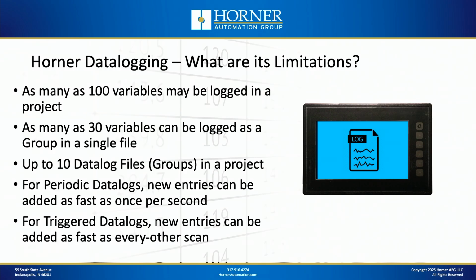Now, we're not going to cover doing triggered data logging every other scan. We're going to cover doing triggered data logging the way it's more typically used, which is only on a specific event, maybe only when a particular sensor turns on or off, that sort of thing.